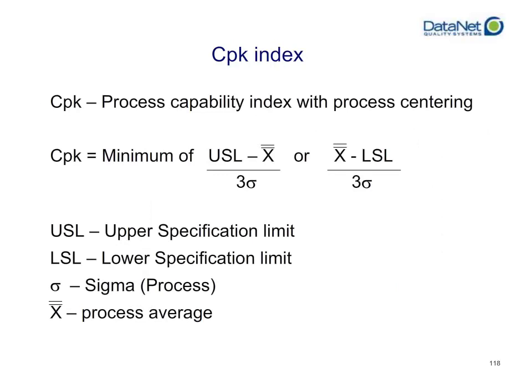If we want to determine the capability of our process, we need to introduce another metric that can tell us if we are not only capable of producing within plus or minus 3 standard deviations, but if we are targeted, meaning if we are centered at wherever we want our ideal output to be.